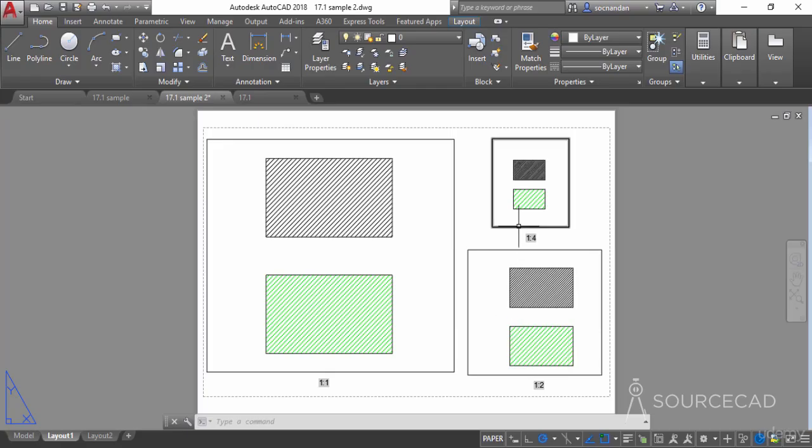Now if you look at the third case, the scale is 1:4. So obviously in this case, when you look at the normal hatch pattern, the scale has been reduced to 4 times of its original value, and the gap has also been reduced to 4 times of its original value. But in this case, again, the same scale has been maintained as it was in the case of 1:1 hatch pattern. So that's the annotative property. When you apply annotative property to an object, you can keep consistent size throughout different scales.